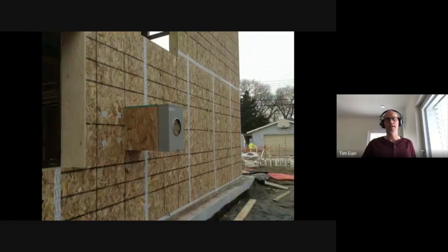Same thing here, building exterior. The initial building was sheathed and air sealed. You can see the taping on the sheathing there, and the electrical meter that needed to go on early being stood off so that it is suspended out there and that there aren't any thermal liabilities between it and the rest of the envelope. So, just little things like that can make a lot of difference.